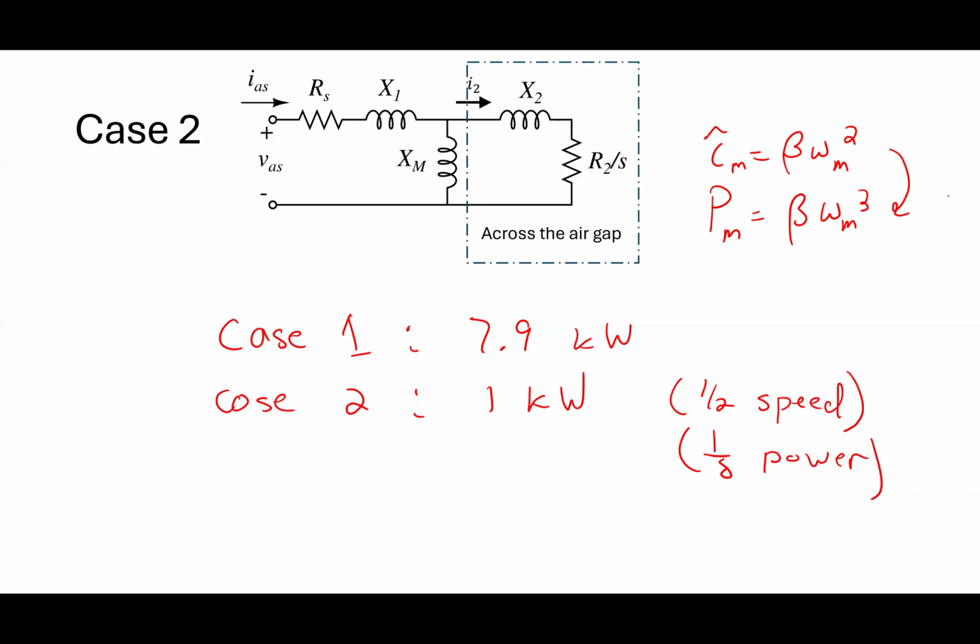So one of the things I ask in the homework is, let's say I had this pump operating 24/7. In case number one, how do I figure out the energy if it ran 24/7? It's a good question. Usually we calculate the energy in kilowatt hours, because energy is the integral of the power, right?